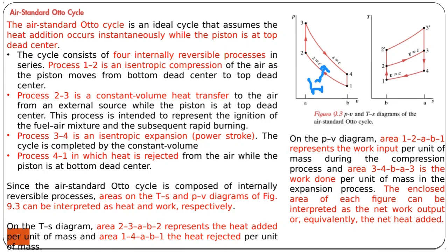Then we add some heat, which represents the combustion heat. Then we obtain work. So this one is work in, this one is work out. And the difference between them is the net work, which is the useful work. Then a process in which the gas is cooled, which represents actually the exhaust process.